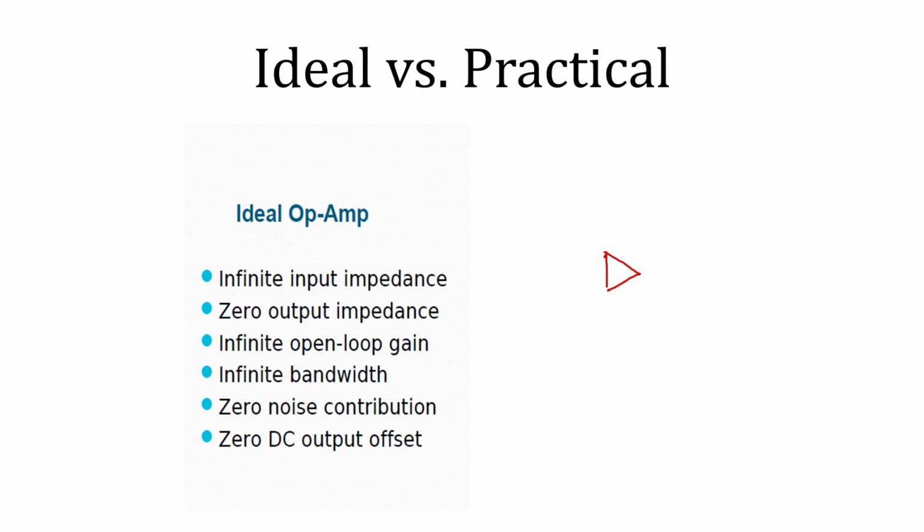suppose this is an operational amplifier, if we connect this operational amplifier to another circuit, its output impedance should be very low, because it should not load the next circuit. As we expect that the previous circuit should not be loaded, we keep its input impedance very high. But when we are connecting to the next one, we don't want this operational amplifier to withdraw much current in this loop, so we make Z0, the output impedance, very low.